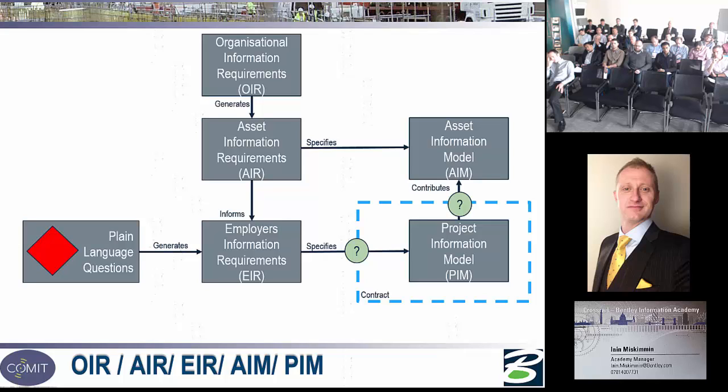So, tier 1 contractor builds up their project information model, and that is fed by across other contract lines within here. My apologies for not putting everybody in here, but it could go on for a very, very, very large diagram. So information is pushed up into the PIM. And then every time we get to the concept, to the details, the construction, the handover, operation, maintenance, etc., data drops are pushed out into the asset information model to allow the organisation to make decisions and get better outcomes for their assets. Any questions on that?